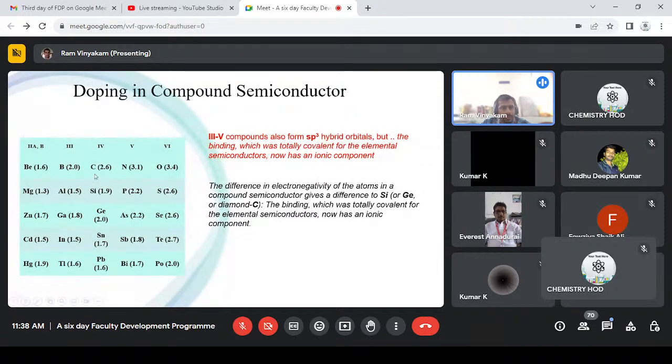Basically, we form III-V semiconductors by using gallium arsenide, gallium phosphide, gallium nitride, gallium antimonide. These are the famous ones, starting in the 1980s. As I told, indirect band-gap semiconductors lack the light-emitting property. So when you need an LED or laser with high efficiency, we have to move on to a direct band-gap semiconductor. That is where the compound semiconductor comes in, also mentioned: gallium arsenide, gallium phosphide, and their alloy combinations will lead to